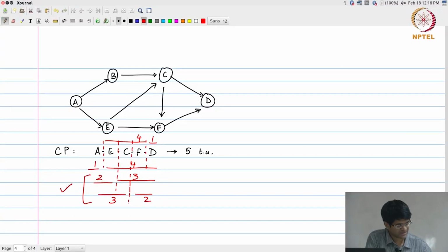So let's consider the possibility that I am going to break the critical path here. And breaking the critical path essentially, as far as I am concerned, involves introducing a register. Okay. Now comes the question, is this sufficient? Can I just do whatever I have done now, which is breaking this path between E and C, right?